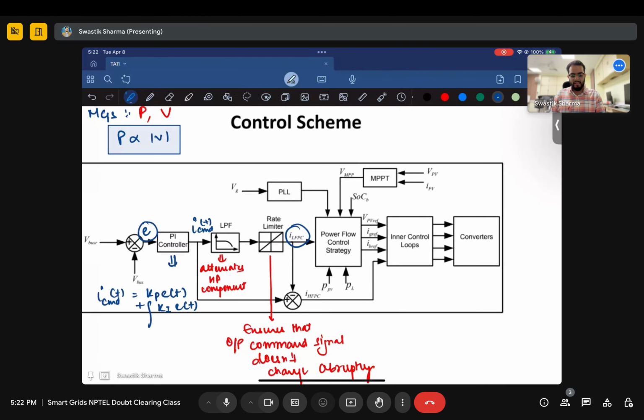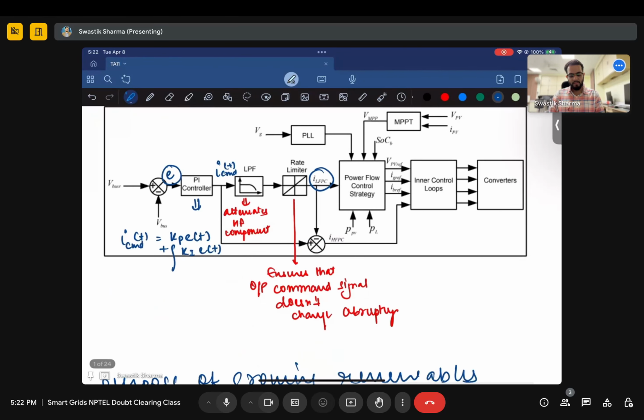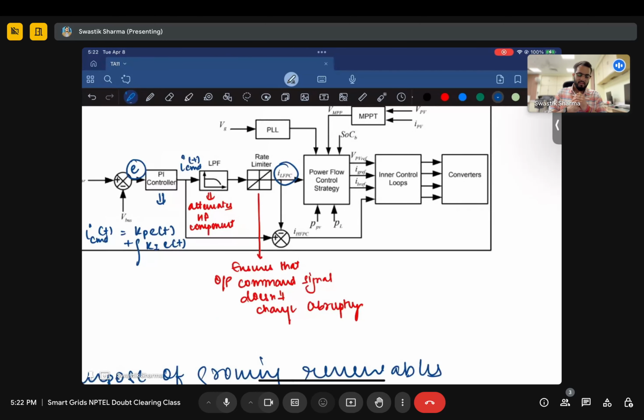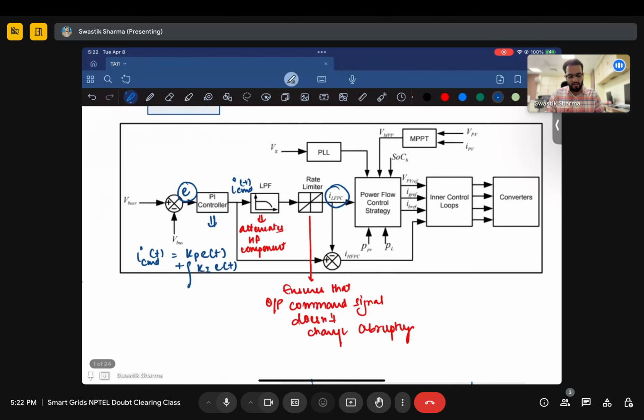And then, before passing these reference signals to each of these converters, we use a second stage of the control, right? From here you can see that earlier we had a bus reference voltage and we were measuring the actual bus voltage, and based on that, we were controlling how the individual storage devices need to behave so that the bus voltage closely matches the reference voltage.